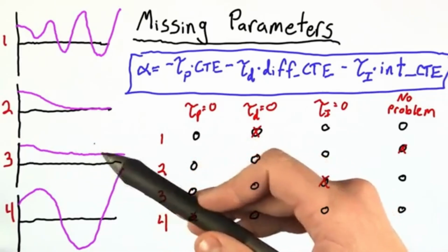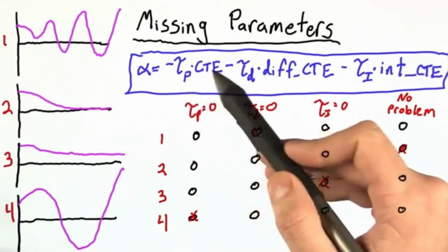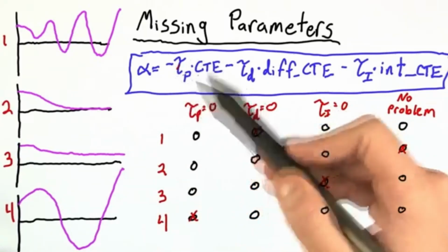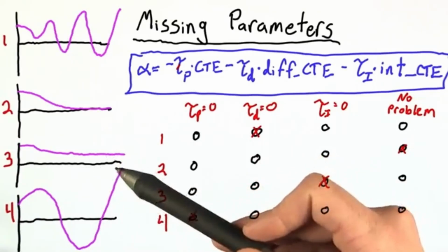That's because we're reaching this steady state where the robot's upward drift is being balanced by its downward tendency caused by this term, and though we reach some sort of steady state, it's not the steady state we want, which would be right on the track.